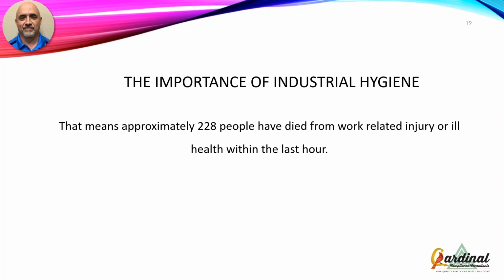We don't understand the chemical exposures. We don't even understand what the exposures are. One of the problems with that is we rely heavily on safety data sheets. Safety data sheets are not the end-all, be-all. They don't tell us the full story, because when you go back to the dose makes the poison, and the dose versus time relationship, what that safety data sheet doesn't do is tell me how I'm working with it. It doesn't tell me where my head is in proximity to whatever is being generated. It doesn't tell me what controls are in place, such as respiratory protection or ventilation. So we really don't understand the big picture.